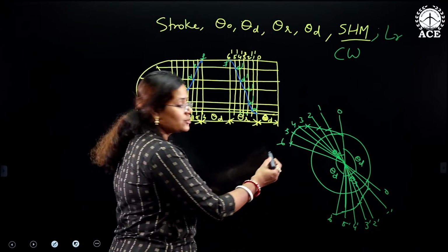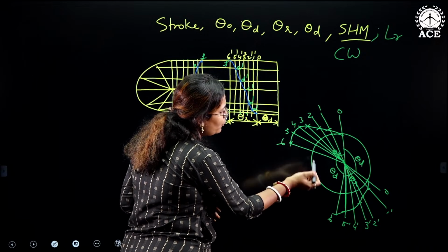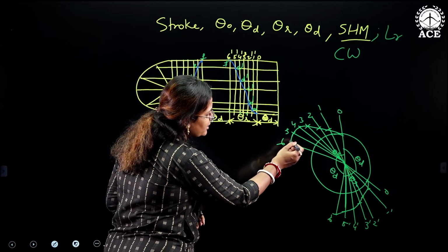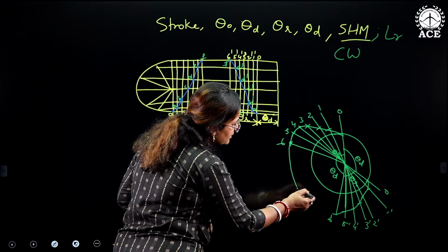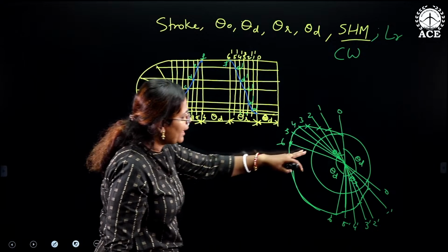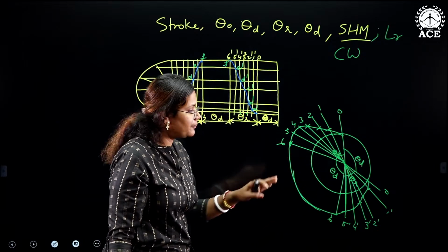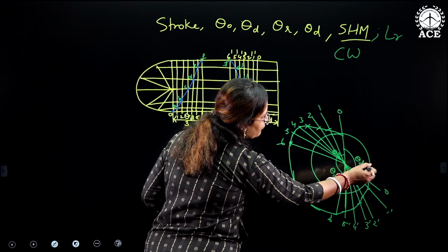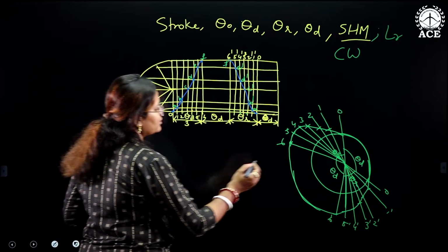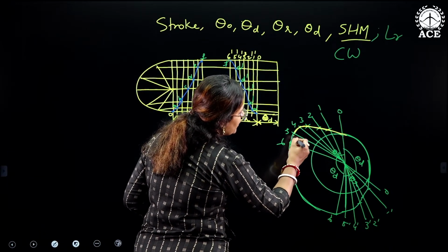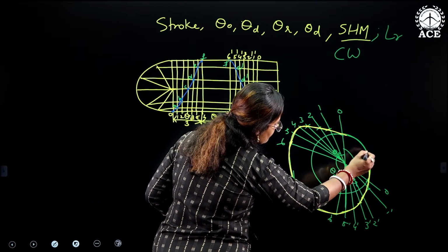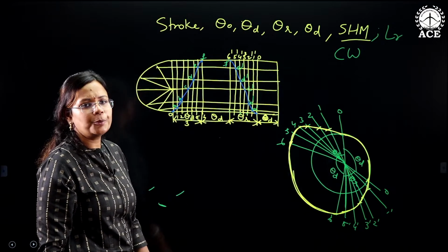Very nice. So here you have a curve where you know that the cam follower is going to be stationary here. So the tracing of the point will be parallel to the least radius, parallel to this particular circle, the least radius circle. And here it will follow the same profile. So let us trace that differently so that it is visible properly. See, this is going to be the profile of the cam.